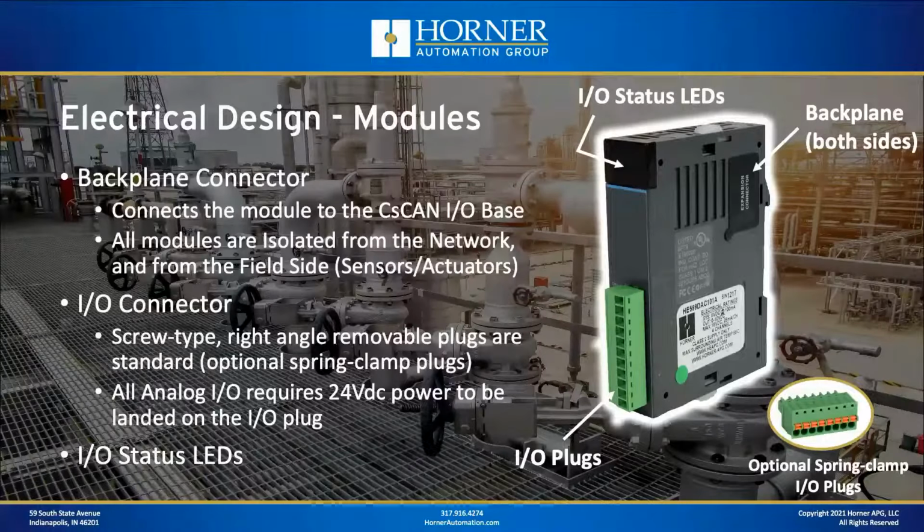Now, depending on how much noise we're talking about and how many analog channels you're talking about, that's really what we're talking about in terms of the magnitude of what kind of difference it could make. It'll probably be pretty small. But if you're looking to optimize your system, having a separate small power supply for the analog circuitry could be something you might want to do.